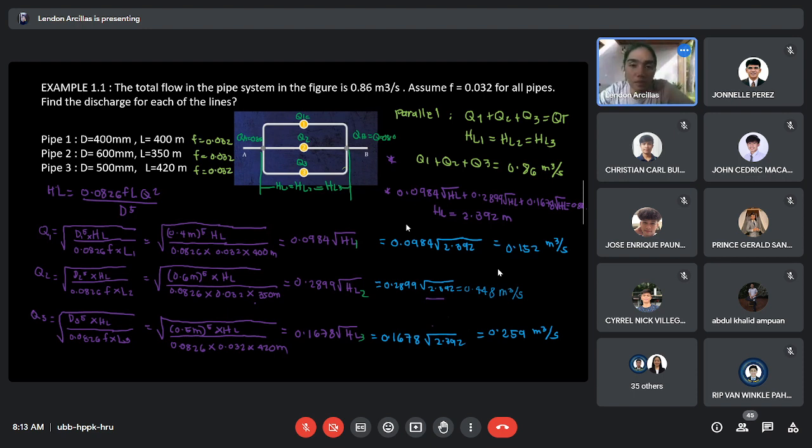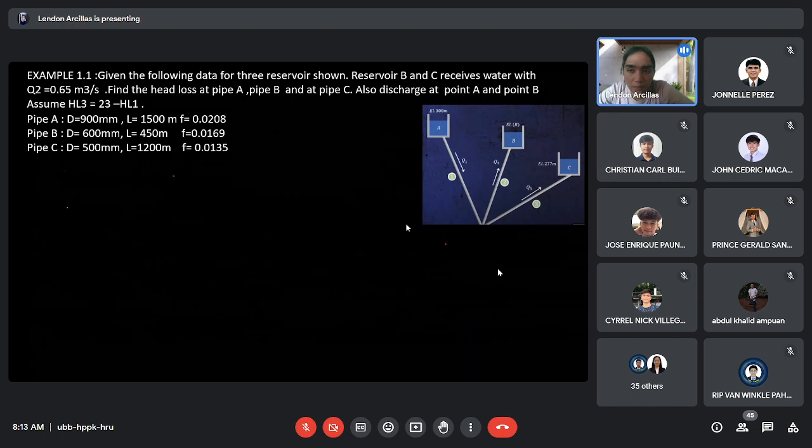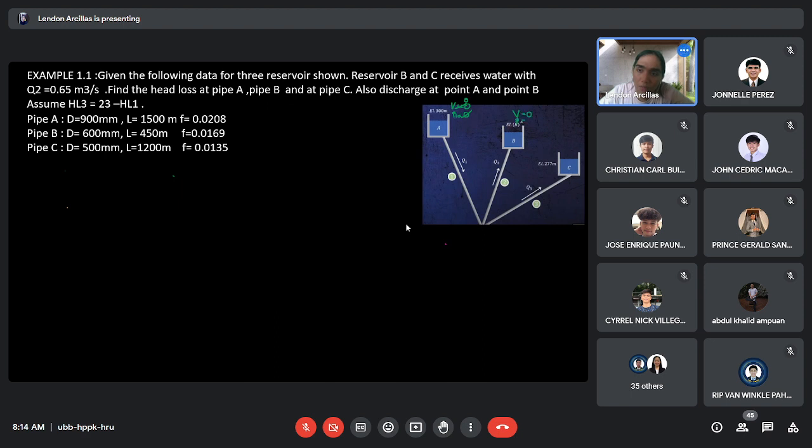Next is how we are going to solve a reservoir. Again, pag reservoir guys, ganito, V1 and V2 is 0, ang P1 0 or P sub A. That is why yung ating mga energy head dito is magdedepende na lang sa Z. Z sub A, Z sub B, and Z sub C. Since makakancel na yung mga V sub 1 and P sub 1, which is used dun sa ating pressure head and kinetic head. So how do we solve this type of problem?